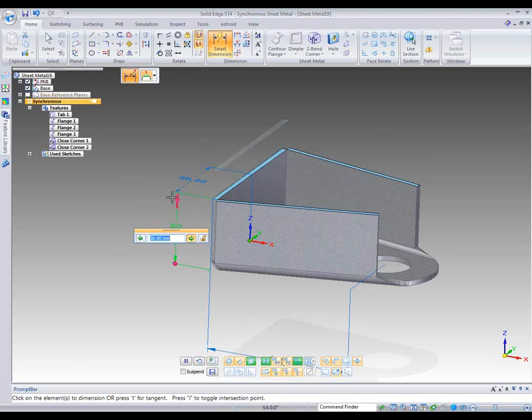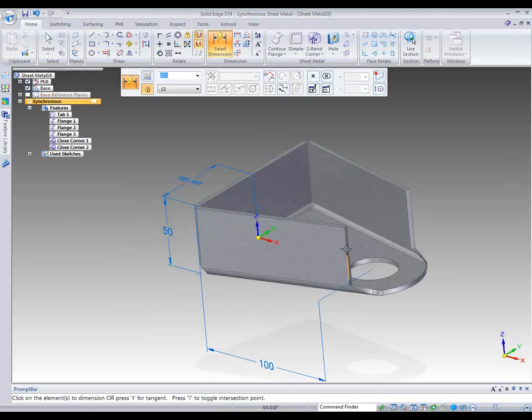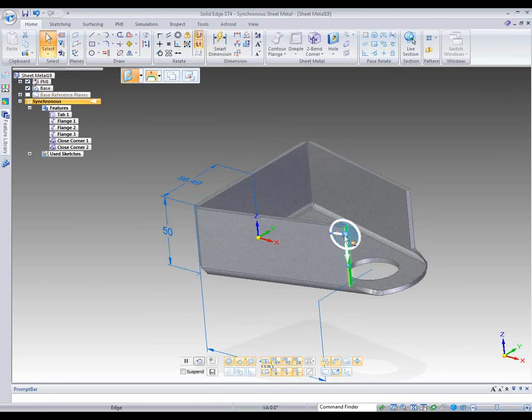You'll notice that I just affected that face to begin with. It went blue, and because of my live rules here that's inferring what I want to do from the geometry, it said, okay, I'll pick up the coplanar faces and bring those down as well. I could turn off that rule if I wanted to leave those faces high. Obviously I don't.